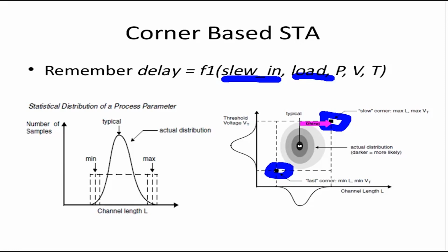If we meet all the timing constraints in both the fast corner and slow corner, most of the chips manufactured under such conditions will probably meet frequencies at least maybe 10 to 20% greater than 1 gigahertz. It might also happen because STA is pessimistic. Probably you will appreciate the pessimism of corner based STA when we discuss variation.